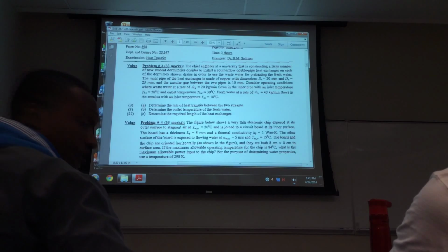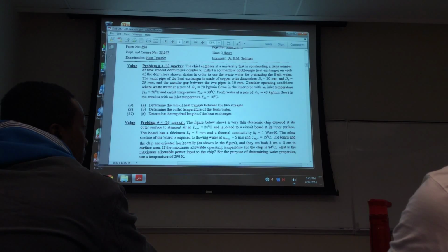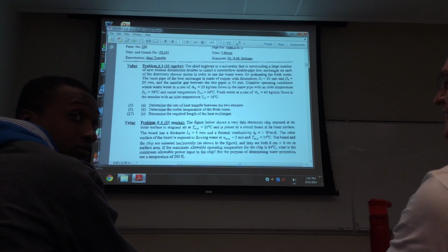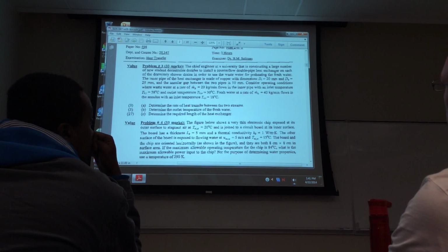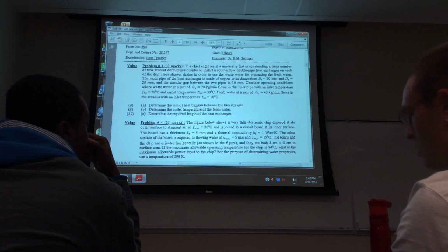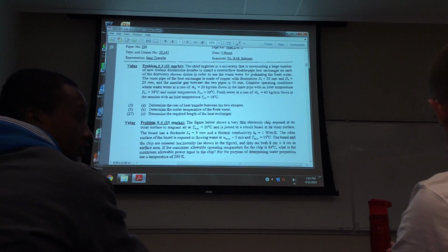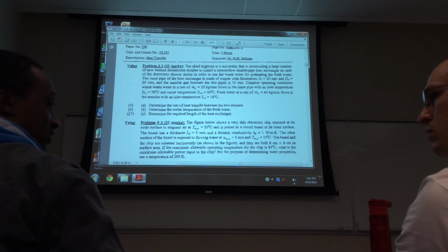Well, the inner one is standard, right? The inner one is just a standard chapter 8 Reynolds number. The outer one will be a non-circular duct, won't it? You have to have a hydraulic diameter for the annulus. Oh, there's the trick, right? So 4 times the area over the wetted perimeter. I think it turns out to be DO minus DI, isn't it? Isn't that the hydraulic diameter of an annulus? So you have to use the hydraulic diameter, otherwise it's exactly the same as chapter 8. There's a table, but the table doesn't make sense.